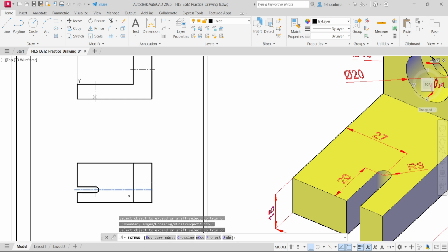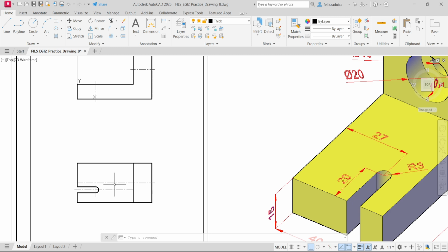And go and tap the ends of the lines here. And tap enter. And now somewhere along here, I have to place a line where the planes offset from each other. So give the line command, and then NEA enter to get the nearest point here, for example, and then get the perpendicular on this one, enter.